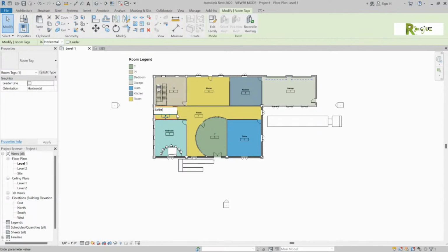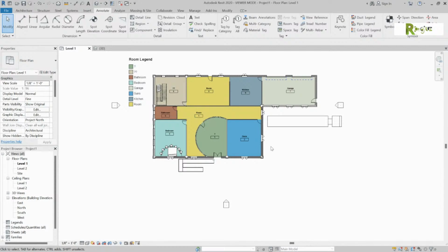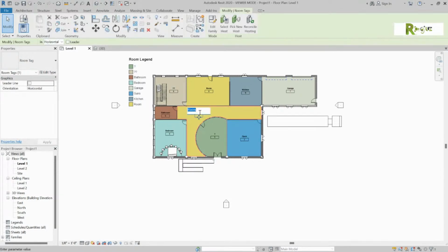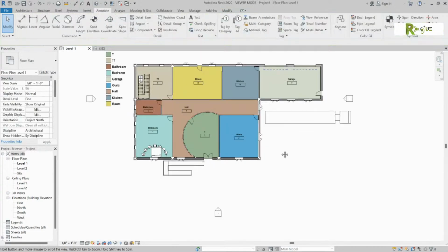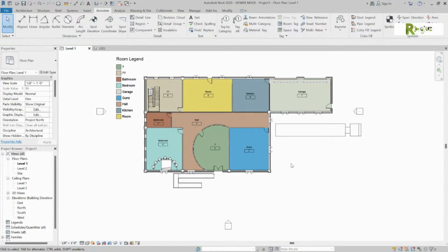And you see how that's all interactive, Tyler, because that's where it really comes in powerful. Now, the nice thing is if you're smart and you're doing a job like we're working on right now, you might say the electrical rooms, I want to make all those red so they jump out to me so I know not to run any ductwork or pipe work above any electrical rooms. Just an idea on how to be able to use that. So if you hit escape 2 times,